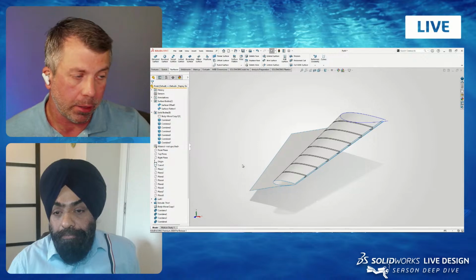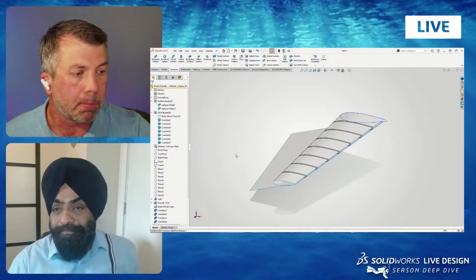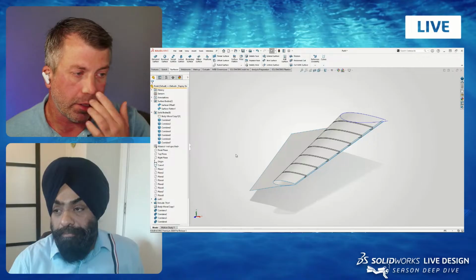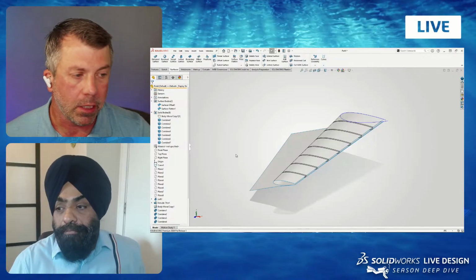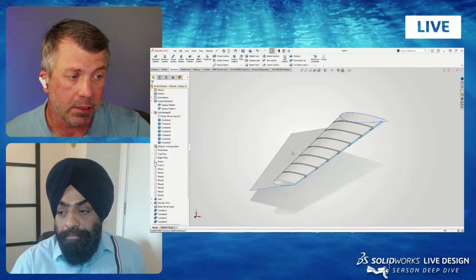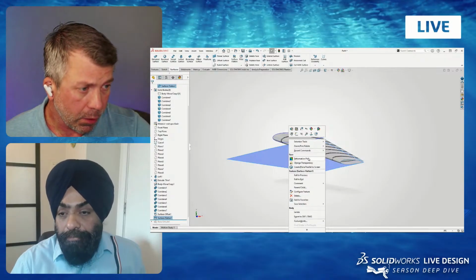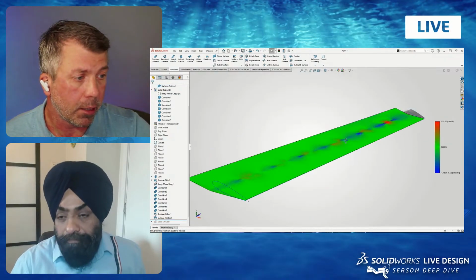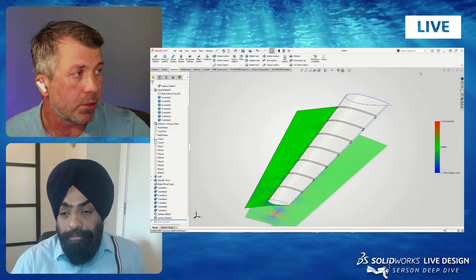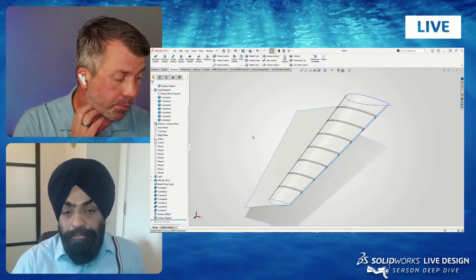It doesn't account for material stretch, right? So if it is sheet metal, we were doing it in one big piece. There's obviously some physics that occur when it's being formed. But composites, this is a great example. And I keep thinking RC planes, or if you wanted to 3D print a lot of the ribs and then come back and wrap it with a composite of some sort, you're going to be able to get the exact pattern based on this shape. And you can right click here, look at things like deformation plot and so on to see where you might have extra stretch that occurs. This is pretty minimal. We're getting 2%. So it's a cool feature, but again, requires a little bit higher level license.